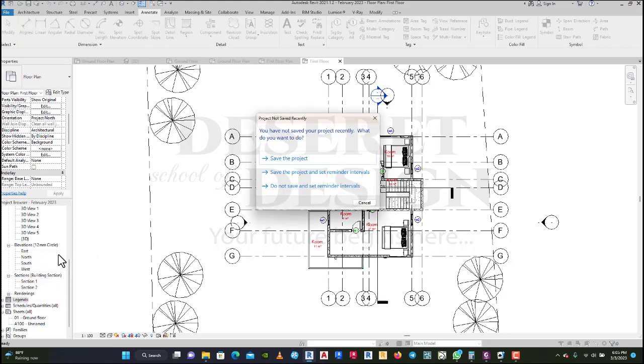Now in case you are doing a window and door legend, you should be mindful of the number of doors you have in your project and the number of windows you have. If the doors and the windows combined is not even more than 10, you don't need to do them separate. You can do the whole thing on one sheet. But in a situation where the doors are a lot, maybe you have almost like 10 doors, then the windows almost like 12, you can't all have the same. You have to separate them. So you do for window on its own, then do for door.